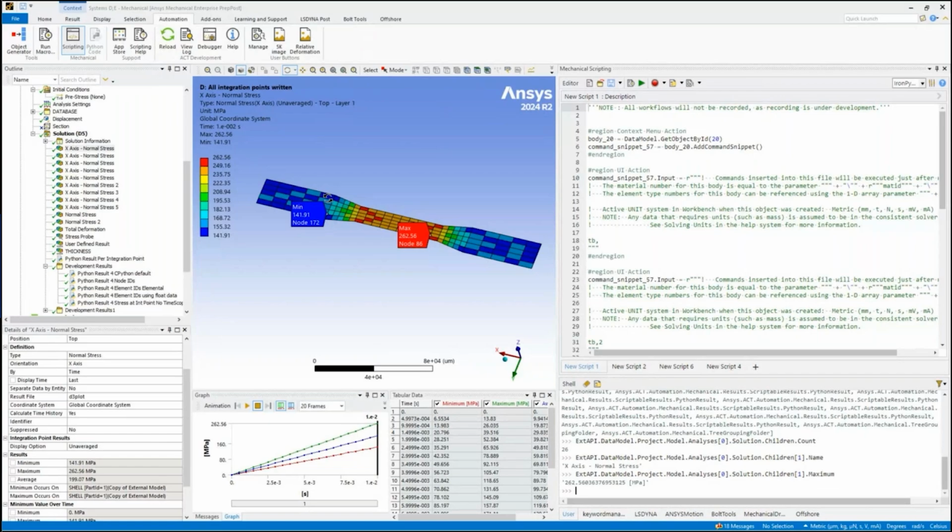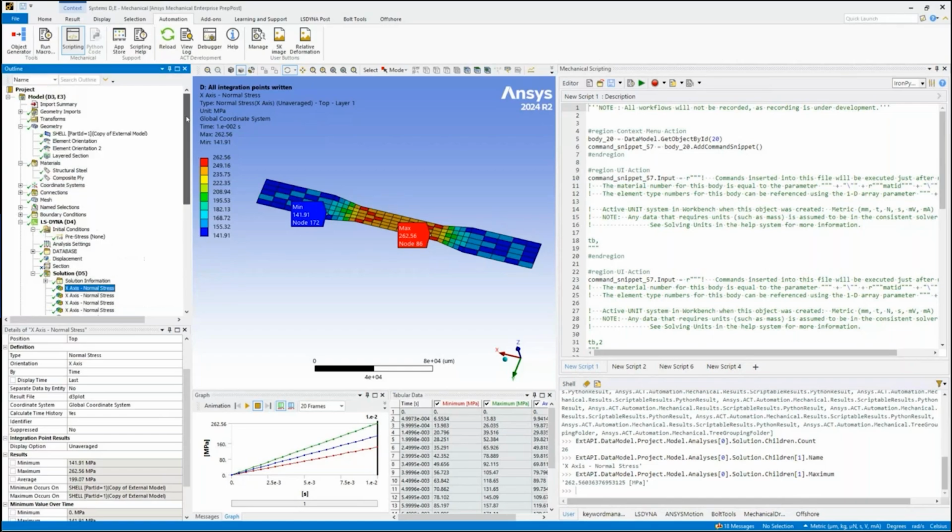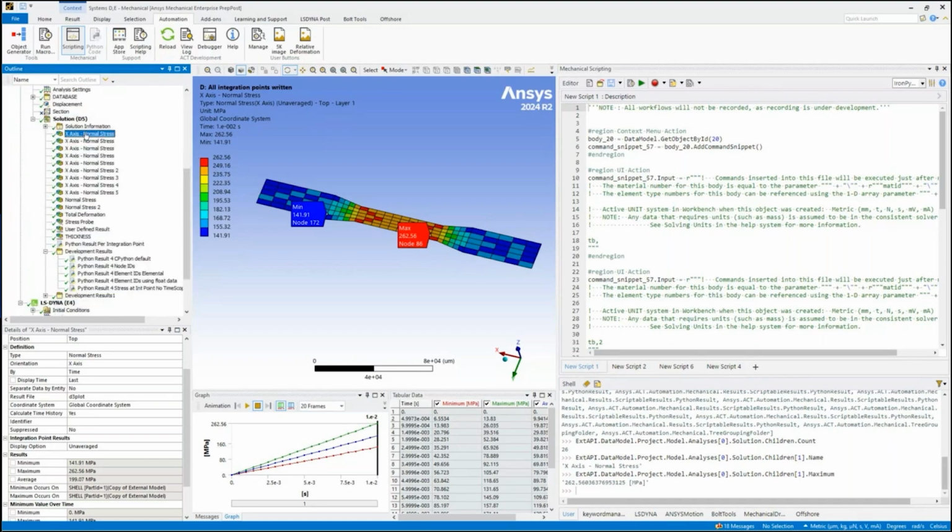Which you may think, oh, well, what's the use in that, Rich? Why is that particularly useful? Well, in this instance, if you're doing an LS-DYNA, this is a layered shell. So we've got a composite section here on these layered shells. Now, by default, if we're using Ansys Mechanical to post-process this, we can only look at the results at the top, middle, and bottom layers. So there is no native way of post-processing every different layer within this layered shell, just using Ansys Mechanical.